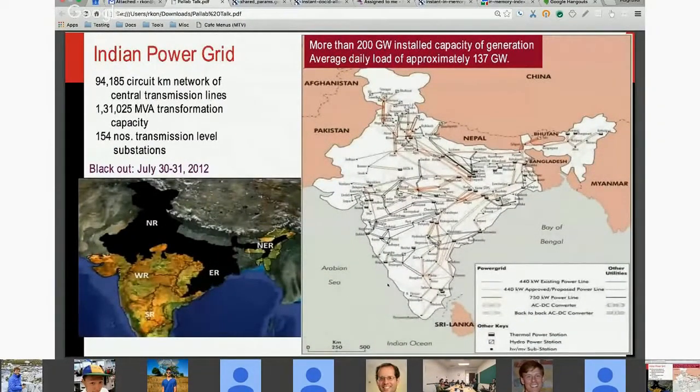There is another area where this IIoT kind of application is already in place, and that is in the power grid sector. In the past, monitoring power grids was a big problem, because it's a huge electrical system. Previously, when people sensed the voltage, frequency, and the rate of change of frequency of voltages at various points in the grid, a standard problem was how do you get a global snapshot of the grid? Because if you are not measuring them all at the same time, then there are a lot of disturbances happening all the time in the grid, so you will not get a picture. Those of you who are in distributed computing will have learned of Lamport's algorithm for global snapshots. It's the same problem. How do you do that?